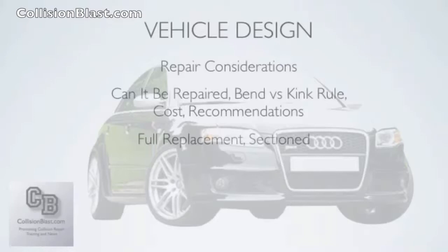So the cost is something you want to look at as well. And also recommendations. There are some parts where the manufacturer wants you to replace only, like we talked about, the ultra high strength steel and the boron. You cannot repair those. Those are replace only. For some of your parts, the manufacturer only wants a full replacement, and that means replacing everything at the factory seams.